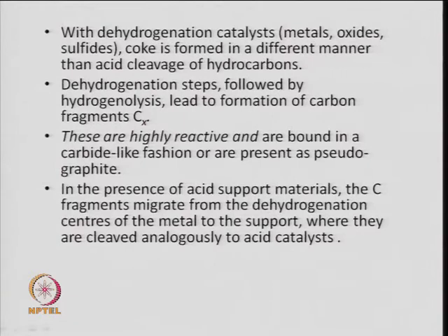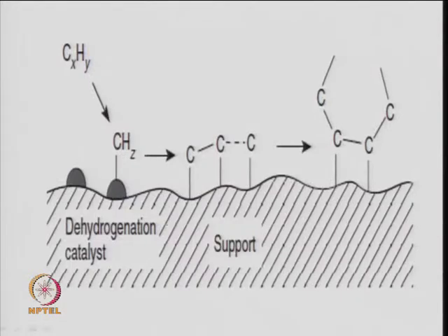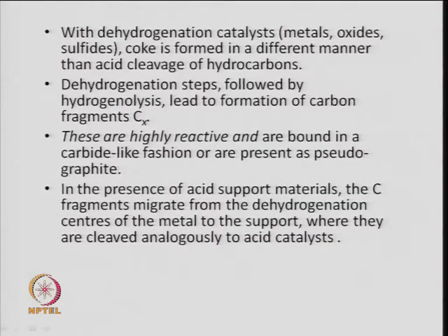If you just look at the hydrogenation or dehydrogenation catalyst, which is just the mechanism of coke formation shown here, a surface, a dehydrogenation catalyst, and you have a precursor, a feedstock. It can be the dehydrogenation, when you look at the formation of the aromatic hydrocarbons, and they tend to form coke. So, basically the dehydrogenation reaction is nothing but removal of hydrogen from the feed. So, it can be something like ethane dehydrogenation and you get ethylene, which is a kind of cracking basically,